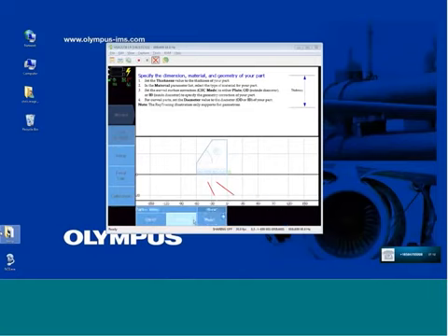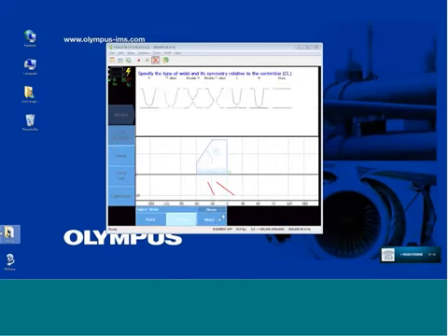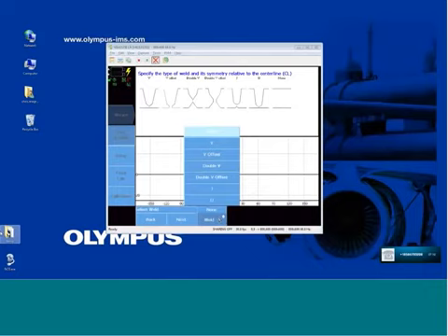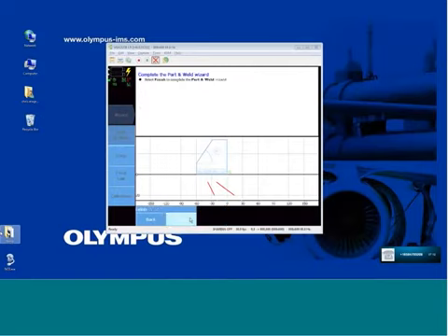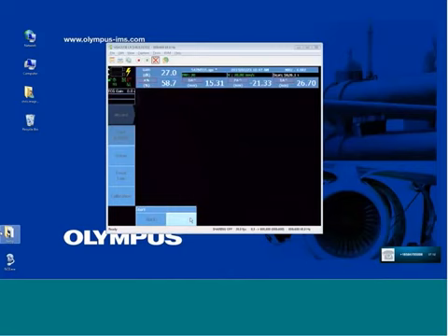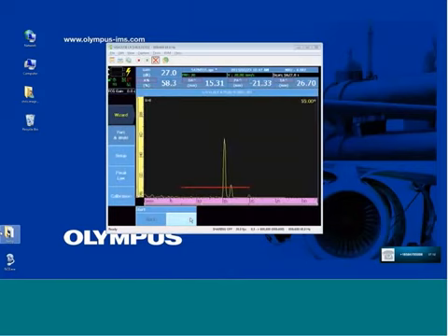We select next. When we get into weld inspection in a later section, we will also add the weld overlay. At this point, for just S-scan manipulation and verification of beam parameters, we will leave the weld off for now. So we've completed the part and weld, or part 1 of 3 of our basic setup, by assigning those parameters to the setup.